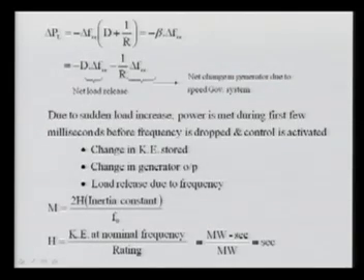So I can say the change in the loading of the system will be equal to the change in the frequency with the minus component beta, and we can write in this term. Again I want to explain here. Now this change in loading has two components, that is D plus change in the steady state change in the frequency, and another component 1 over R multiplied by change in the frequency.